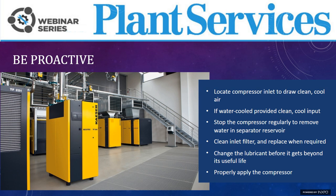Typically we see a lot of undersized machines, or your plant might have a system that's oversized, or where the compressor duty cycle is very low, like Tim mentioned. Other items to consider would be bearing life, which is directly affected by operating conditions, the environment, as well as duty cycle. One thing that you can consider would also be vibration analysis, which would require a baseline prior to startup, and then can be monitored continuously or via discrete points in time.